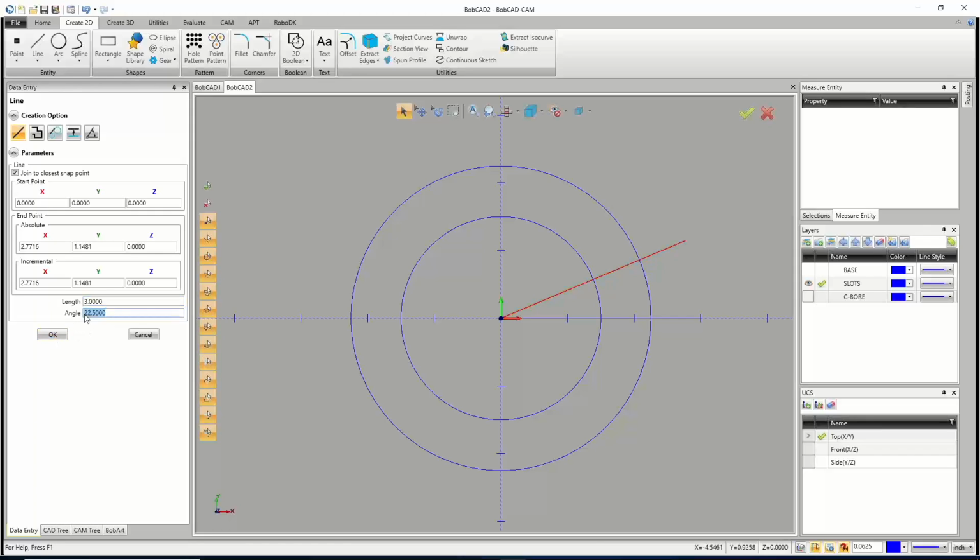And then all I have to do is change this number to a negative. The reason I do it this way instead of going with the 45 and trimming things out is so I have everything clocked at my 3 o'clock position. I could also just do it to 45 and then rotate it 22.5 degrees or negative 22.5. That would work as well to clock me back at my 0.